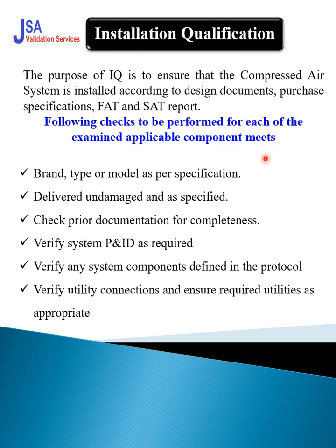Then installation qualification. After all this, we go for the IQ. The minimum checkpoints that your protocol or test plan of the IQ should include are test parameters like brand, type, name, model as per the specification, deliverable, undamaged as specified. If it is not done in SAT, then you have the checklist in the IQ, so you verify undamaged or as specified. Check the prior documentation for completeness, all the test certificates and everything. Verify the system P and ID. Verify any system components defined in the protocol.